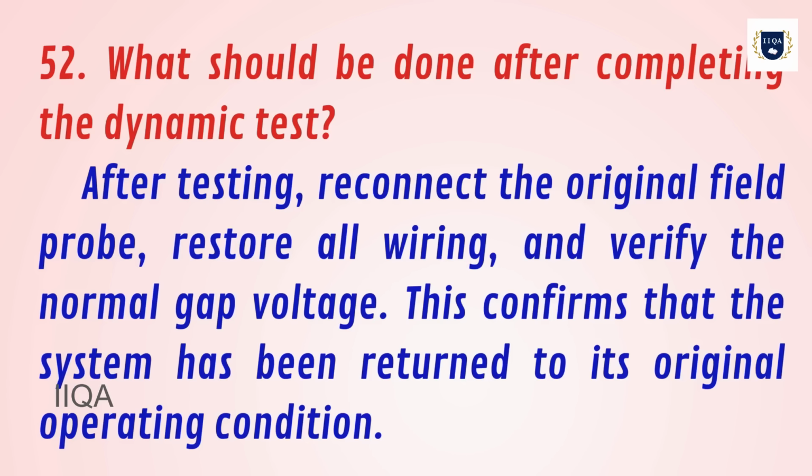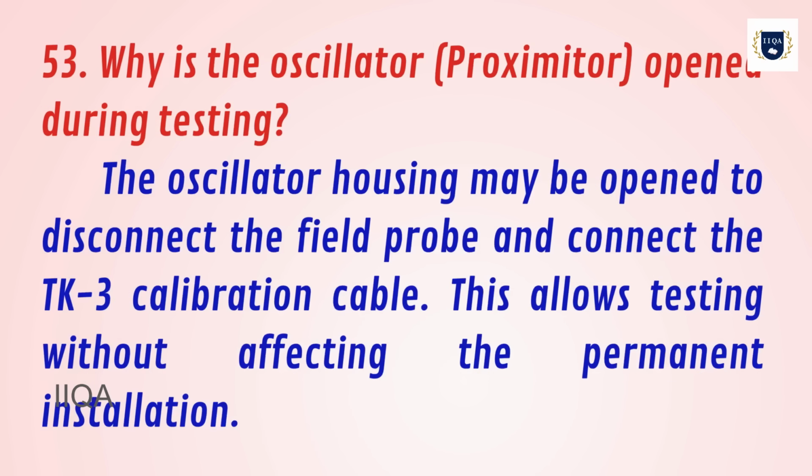52. What should be done after completing the dynamic test? After testing, reconnect the original field probe, restore all wiring, and verify the normal gap voltage. This confirms that the system has been returned to its original operating condition.